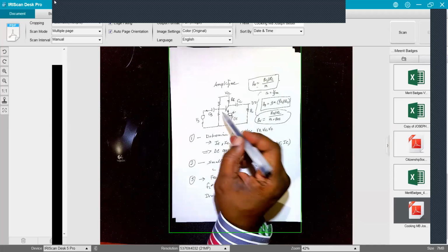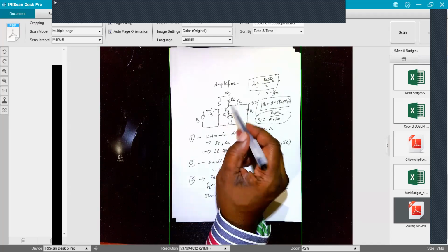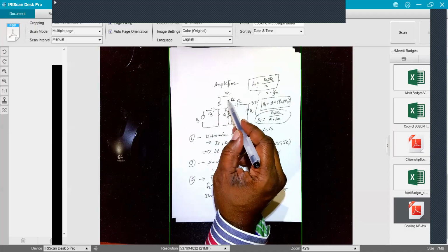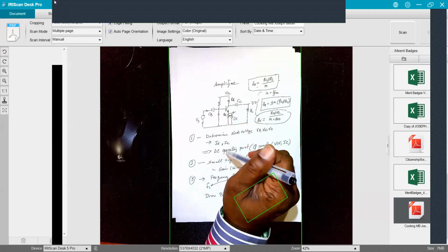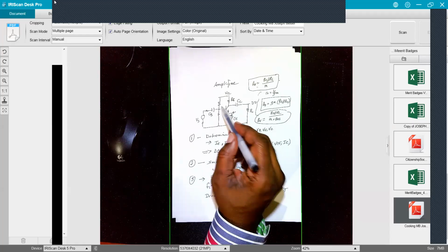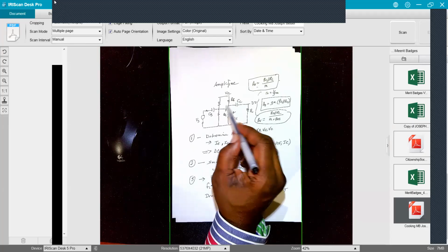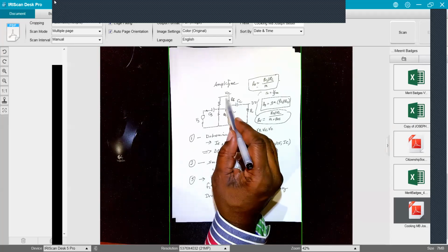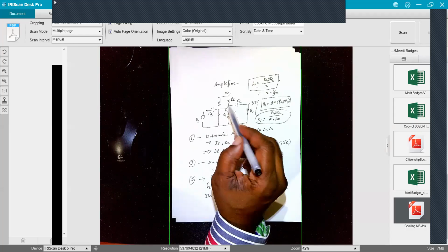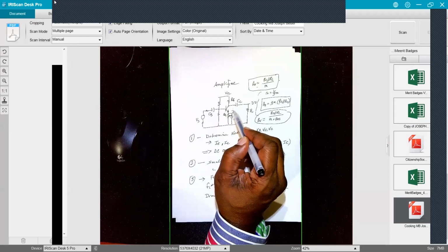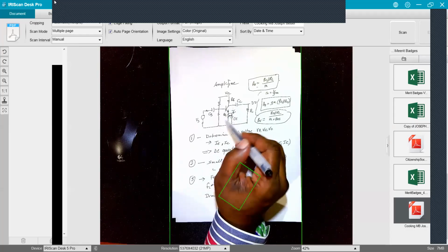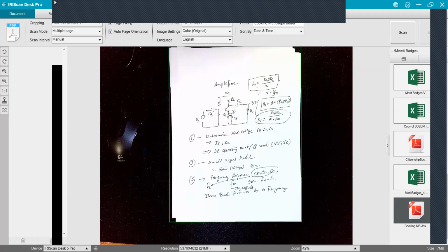You know, I can't go in here and make this resistor way bigger than it should have been, like 10 times, and this whole thing collapses. Now, you will still have VE equals VB minus 0.7. But if this resistor is much larger than it should be, this current going through here will take this node and push it down so far that you're actually outside of your active region for your transistor.